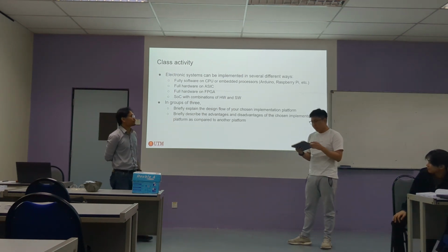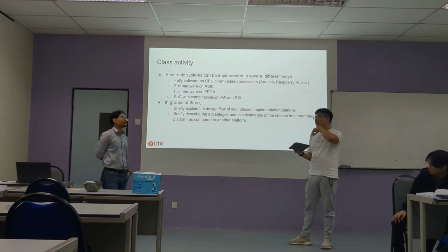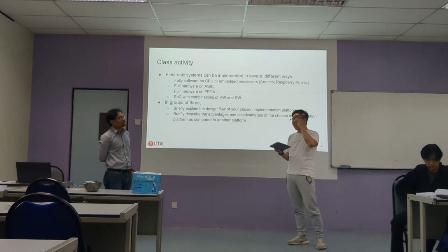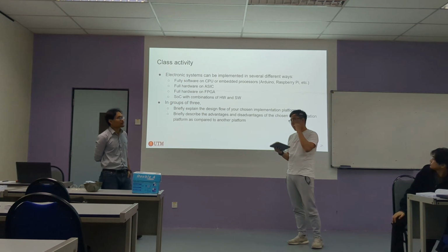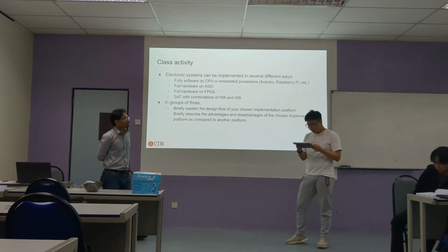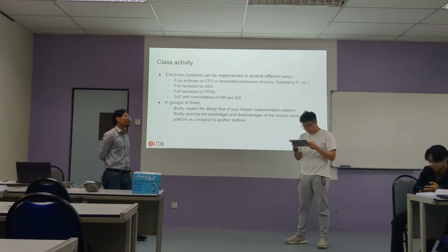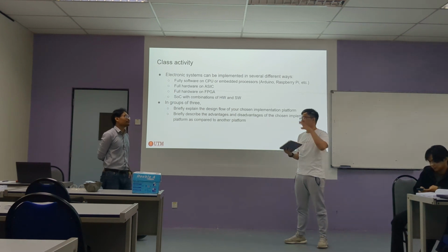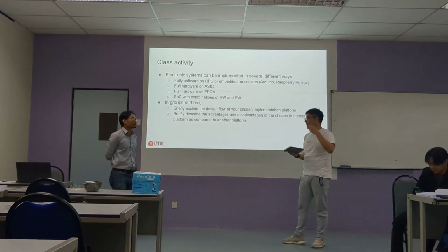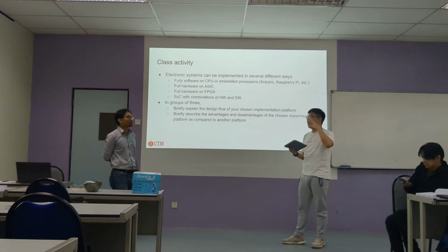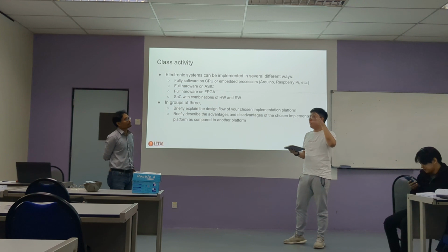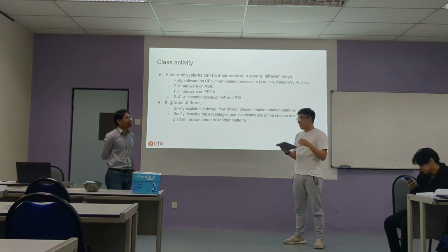For instance, the TPU, tensor processing unit, I think is considered an ASIC, which is a matrix multiplication unit. It just does a specific task, matrix multiplication, so it's more specialized in terms of power, performance, and area optimization. An advantage of ASIC is its flexibility in physical design. You can customize how much I/O, how much GPIO, how much power and area, as long as you hit the specs, compared to FPGA. When you cascade FPGAs, you might have redundant RAM or redundant I/O. Yeah, that's a good point.